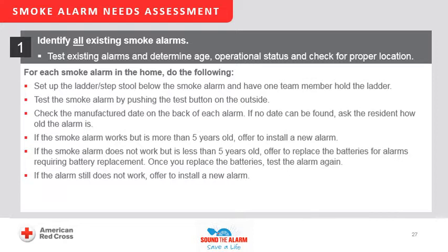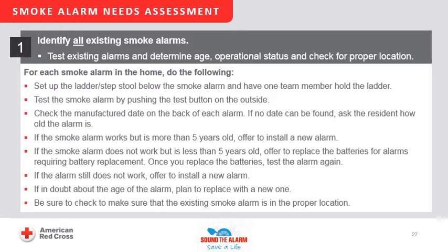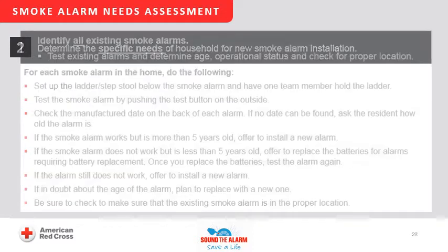Offer to take down the old smoke alarm. If you remove the old alarm, leave it with the resident. Do not remove hardwired smoke alarms. If in doubt about the age of the smoke alarm, plan to replace with a new one. Be sure to check to make sure that the existing smoke alarm is in the proper location.